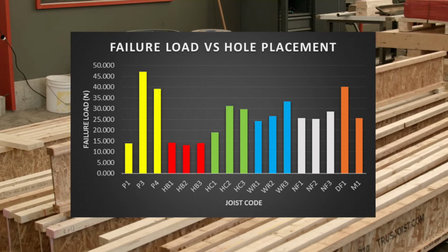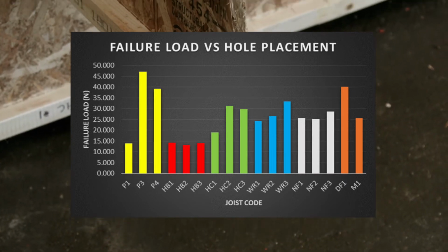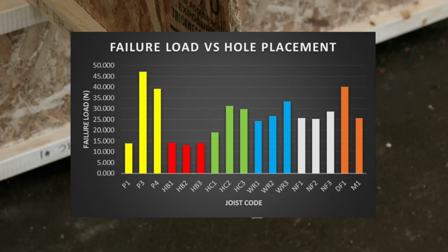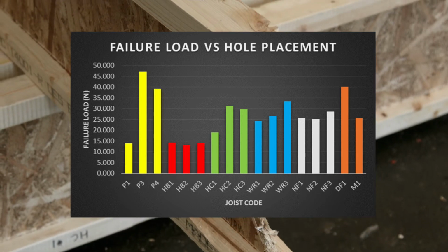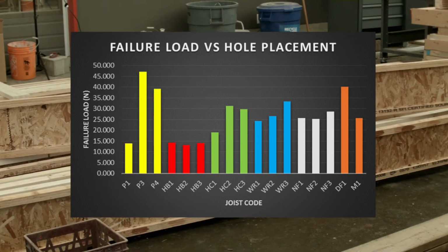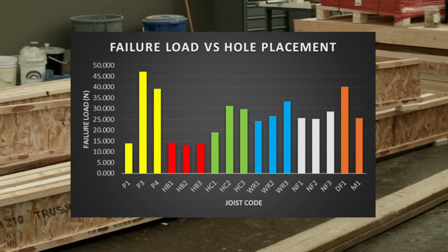wood I-joists. The charts can be downloaded from the manufacturer's website and easily understood by all. Do not memorize one manufacturer's charts and apply them to all. Each manufacturer has different allowances for hole placement. Rules of thumb methods are not always correct and should not be relied upon.